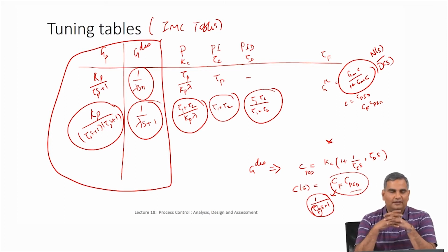So once we have that, then we said okay, you might get the output in the Laplace domain, but ultimately for you to understand all of this you need to get the output in the time domain. So we said the process is you have a time profile for the input, you convert that to a Laplace transform, multiply it by a process transfer function, get the output, and then you do the inverse Laplace transform.